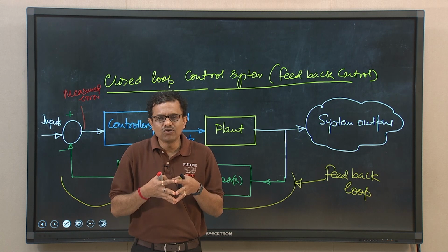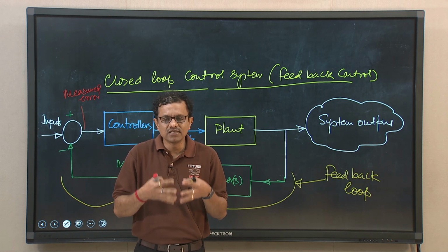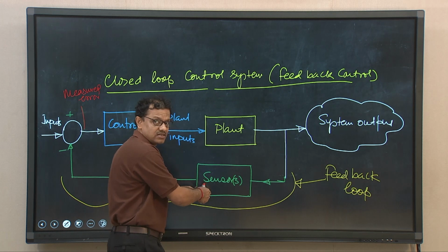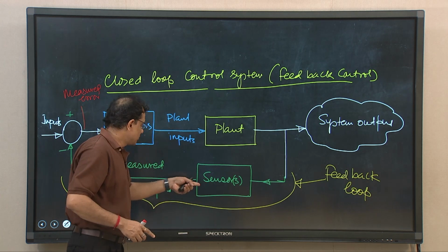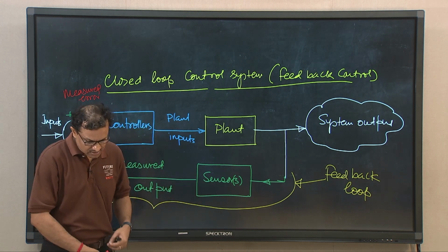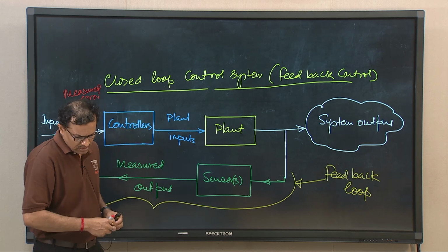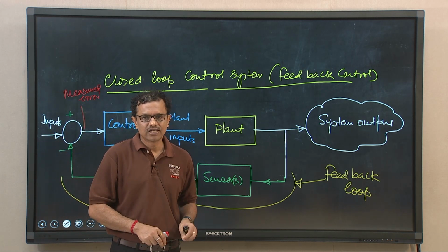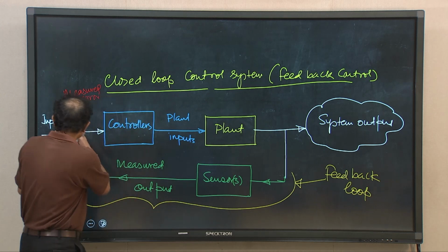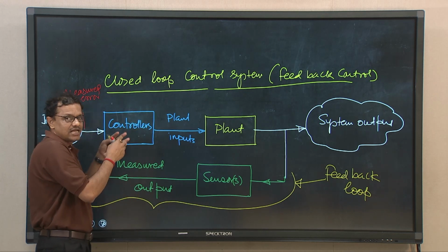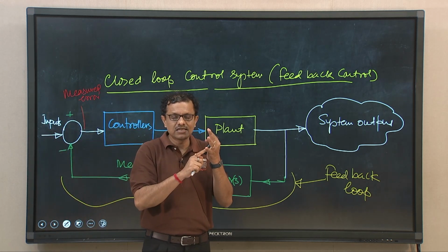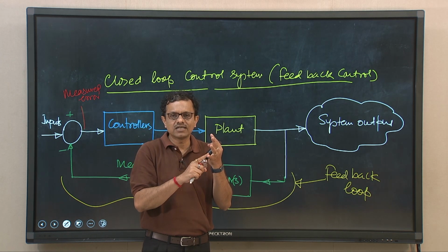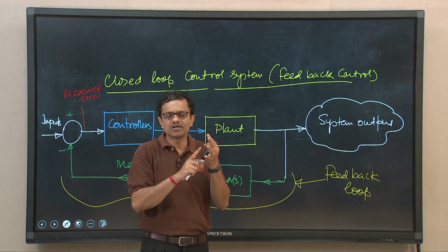This feedback loop allows the system to adapt to changing conditions by utilizing sensors that monitor engine operating conditions. So all these inputs we will be receiving, like pressure, temperature, speed, temperature of the cooling water jacket, temperature of ambient air, pressure of ambient air.